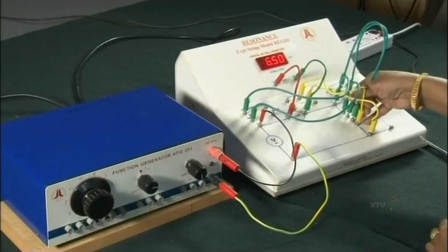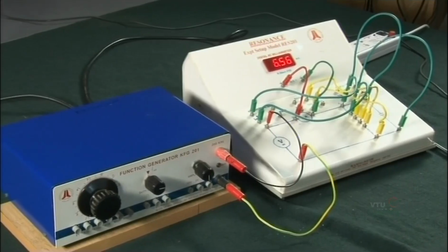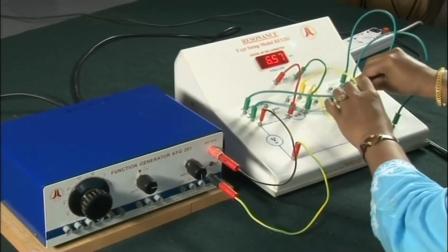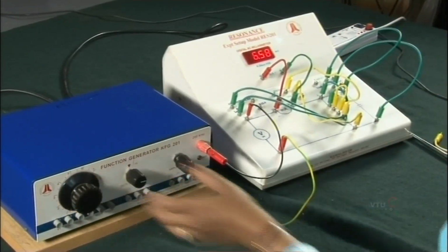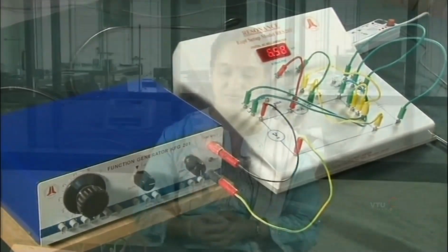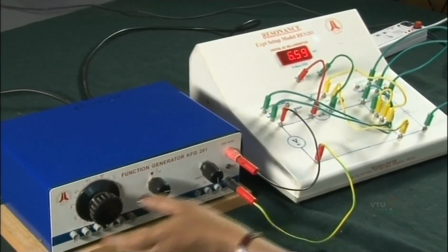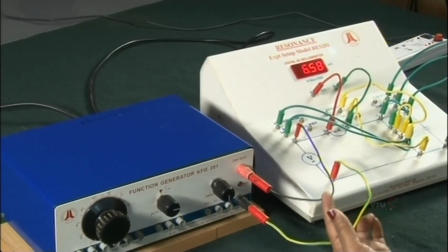This procedure is repeated for the parallel resonant circuit by connecting the capacitance in parallel with the same components, with the same set of values. We connect the capacitance in parallel with the other two, L and R, and we repeat the experiment in the same steps. The resonant frequency of the circuit is the same because we have not changed the values of L and C. So, the circuit resonates at the same frequency, but the current through the circuit, you observe, is maximum initially. So, at 1 kilohertz initial value of applied frequency, you see that the current is showing maximum.